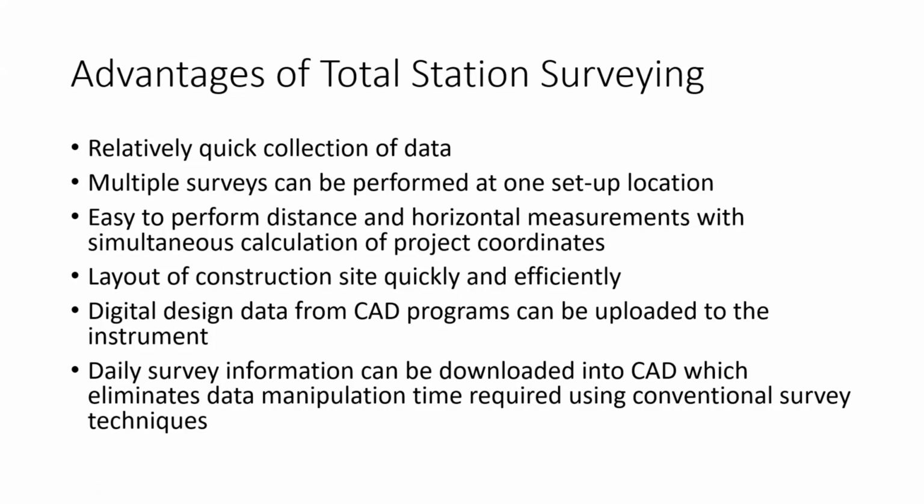One is collecting the data, and second is using this data, fixing the coordinate on the ground. Suppose we wanted to plan a bridge, or we'll take a small culvert. We have the map first. To prepare the map, all the data is taken and the map is prepared. And on the map, we decide the best location of the tunnel, the culvert or a bridge. So on the map, we have the coordinates of the bridge, and these coordinates are fixed on the ground. That is called as layout.